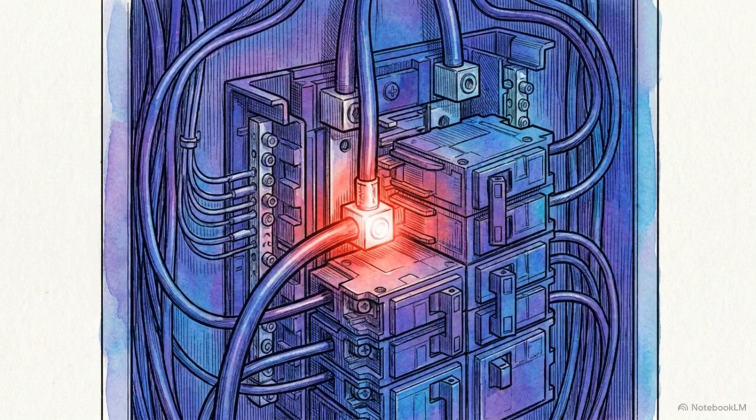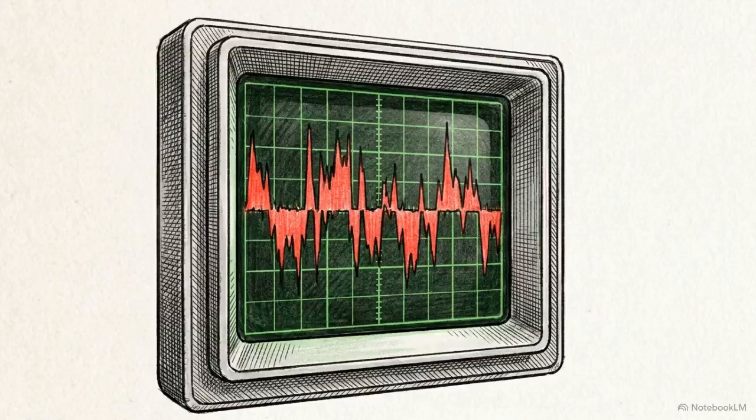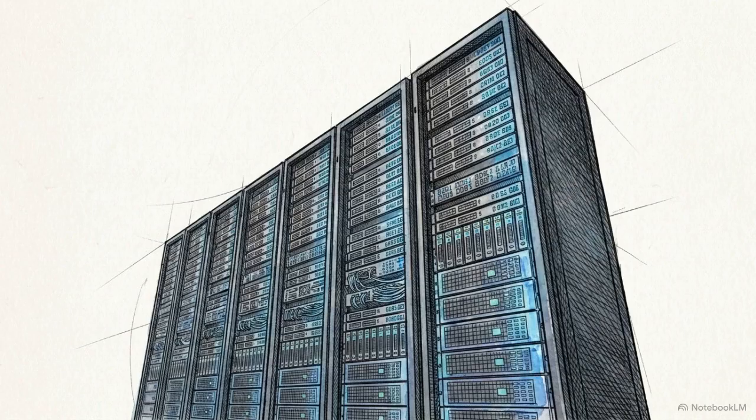This thermal camera view demonstrates thermography. Infrared scanning allows technicians to actively detect high resistance connections, like this white-hot breaker lug, before catastrophic arc flashes occur. In parallel, engineers run power quality monitoring to detect invisible harmonic distortions that slowly degrade UPS components over months of operation. Proper bonding, IP ratings, and thermography actively validate and protect the physical integrity of the power path we just modeled.